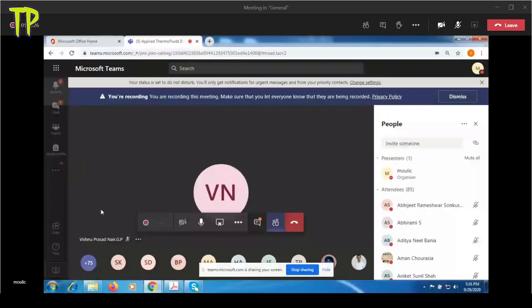All right. Now let us go back and look at this figure of the moving vane of a Pelton turbine. So this is the nozzle, and the water jet comes out of the nozzle and impinges on this vane, which is curved. The vane is moving with constant velocity to the right. And because this hatched surface, the solid surface, is impermeable, the fluid cannot go through. It will be forced to turn. It will be deflected backwards.